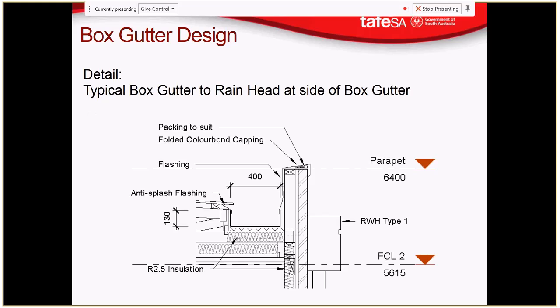You're referring to the other gutter I drew where it had a sloping bit and then flat. Yeah, that's for a different scenario. So with this one here, this is where we have a truss, and that truss is designed to have a strong enough bottom chord for that bottom chord to extend through to here. So it's a truss designed to accommodate a box gutter. So when you tell the truss manufacturer, this is what I want, they'll go, yep, we can do that, but we need to have a stronger bottom chord to be able to do that.